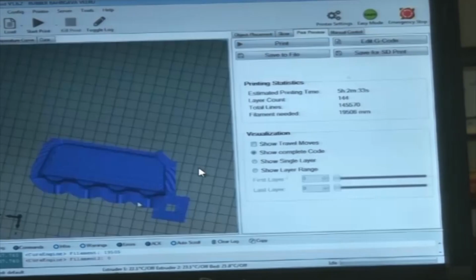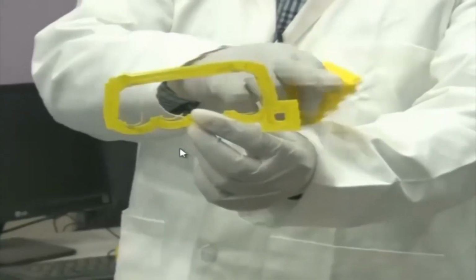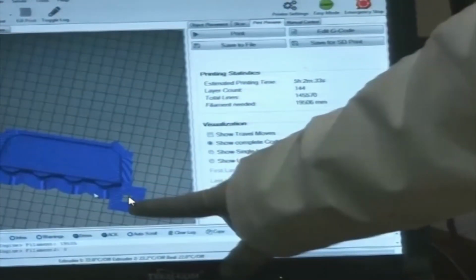Now the slicing starts. You can see that it has made a brim by itself, as it might have found it important. The software is quite intelligent to decide this. You can see this skewer is there. Why is this skewer there? The skewer is for holding. We need to hold the brim layer and take the job off.